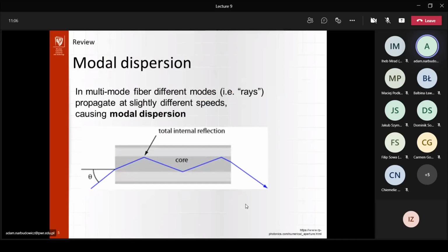Okay. And similarly to the chromatic dispersion, which is based on the frequency, we can see a similar effect with what's called modal dispersion. So this basically means that different modes also may travel at different speeds. And this might be even more challenging, because over here we have two signals which have the same frequency, and just by the fact that they propagate with different modes, they will arrive at different speeds, again stretching our pulse, right? Even if they are the same frequency.